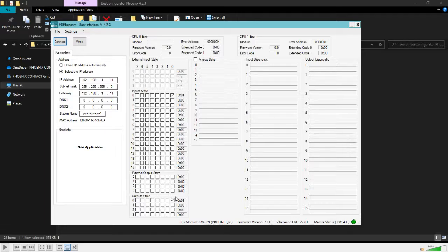So if I toggle my e-stop, you can see input state here is going to drop out. And if you recall, my output state as well should drop out for that. So they were tied basically 1-to-1 there. I'll bring it back on. So the next thing I'm going to do is force an error, and you can see some of the data that you'll get on this splash screen as well.